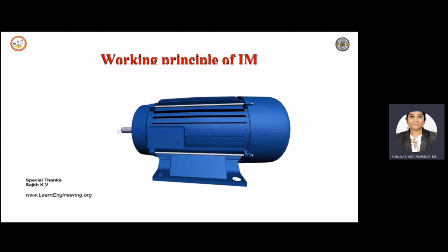When it comes to the working operation, the induction motor works on the principle of electromagnetic induction. When a three-phase supply is given to the three-phase stator winding, a rotating magnetic field is produced, and the speed of the rotating magnetic field is Ns = 120f/P, that is the synchronous speed. This produces an effect of rotating poles around the rotor.